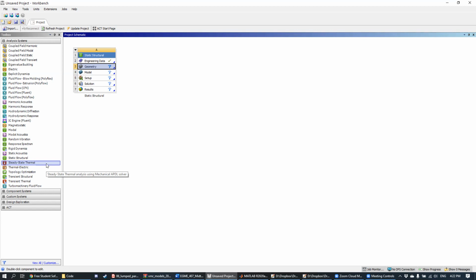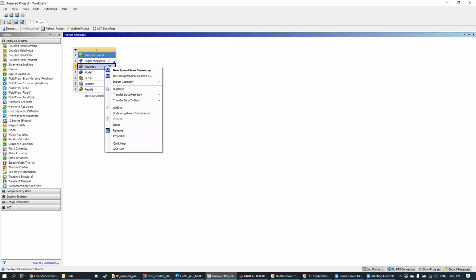But what's more common, especially in professional practice, is that you would use a more sophisticated CAD program like SolidWorks to build your model, and then import that into ANSYS. Okay. And so let's go over how you actually import these kinds of external models. All right. So you're going to right-click Geometry here, and then go to this menu called Import. Once you highlight this Import button, you're going to click Browse.